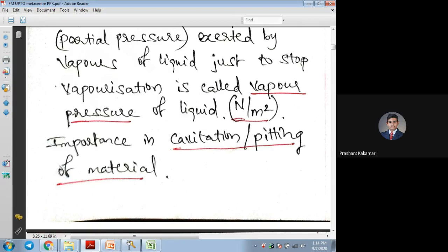This pressure can lead to sudden bursting of the pipelines or creating cavities in the pipelines or containers, so that we don't get complete filled flow. This is one of the problems of cavitation. So one needs to maintain a proper low temperature or pressure so that vaporization does not occur in the given liquid.